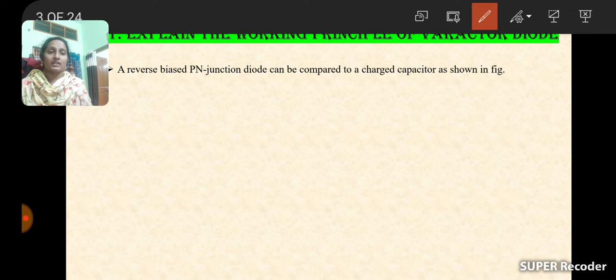Second remedy: improper tapping of the coils will produce instability, so you tap it properly. Temperature variations also will affect, so to protect from temperature variations, provide proper shielding for the transistor. And transistor parameters also change due to high heat, so you also use heat sinks. These are the various remedies to protect the oscillator from instability.